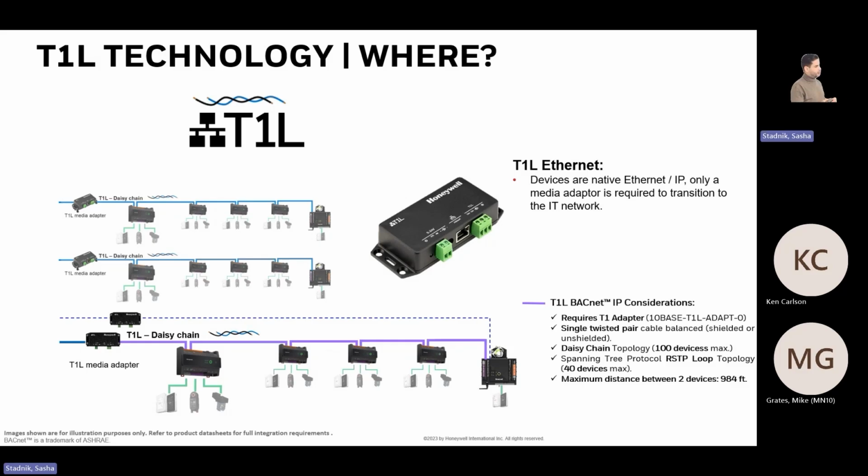Now, these guys were so brilliant because they were saying, okay, we have all these IP devices out there for PLCs. What happens if we design the T1L? Can we reuse even the Cat5, Cat6 cable? Because Cat5, Cat6 cable and the Cat4, they're coming in pairs. And the standard of T1L is a twisted pair. Shielded, not shielded, stranded, not stranded, whatever you want.